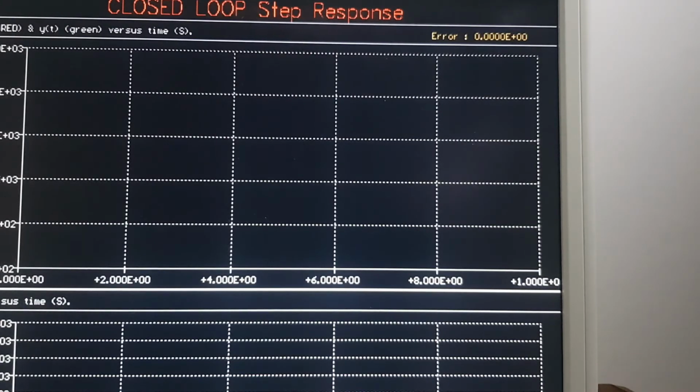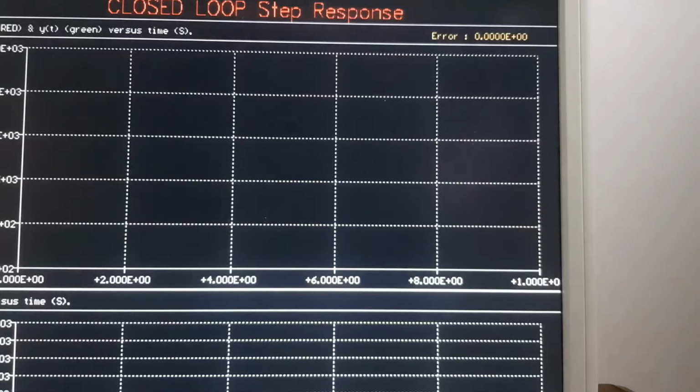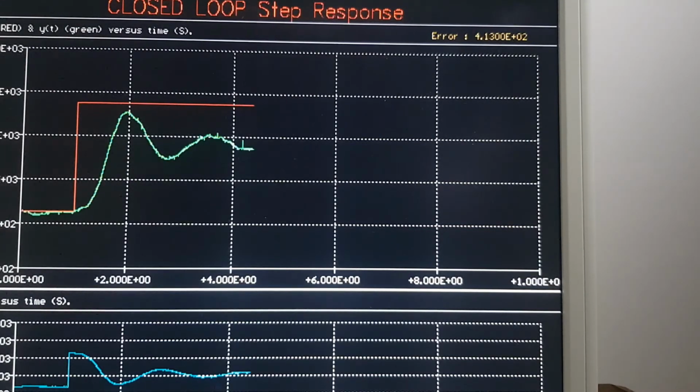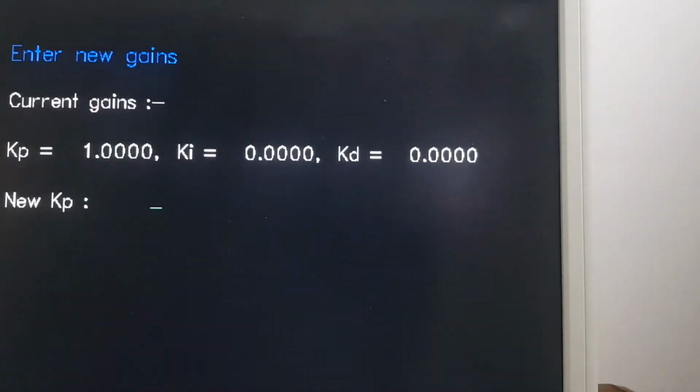So if we go back to a gain K of, let's say, 1. 1 is not a special number, just chance for this process. But with a gain of 1, we're probably getting our best type of response. So our steady state error is about 1/3 of the output. It's not too oscillatory. Maybe 1.2 is better.